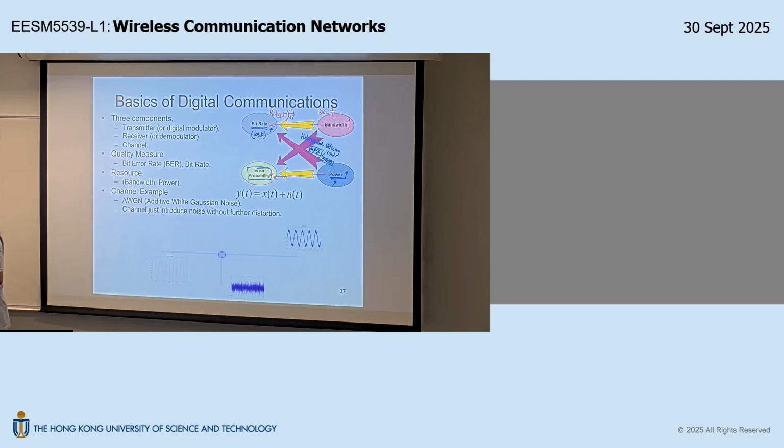Is that okay? What about this? If I ask you to put the 16 points using this configuration, how many freedom do you have? Only 1 freedom, because r is the same across all the points. So the only freedom you have is theta. From an optimization language, you are optimizing these 16 points on the two-dimensional space under the same constraint, but this one has less freedom, this one has more freedom. The one with more freedom, you will end up having a better design, right?